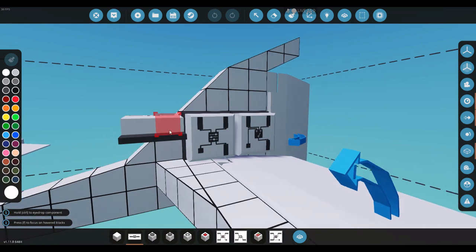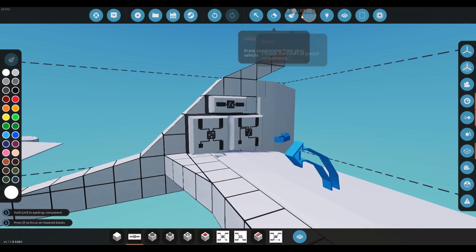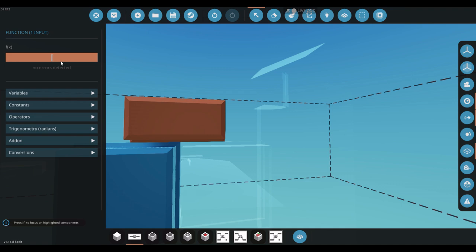And we'll put in the function block over here to keep things nice and simple since we're still working on altitude hold. So for the function block, remember, we were getting 5 values greater than what we wanted. So we're going to hit x minus 5. If you were getting 5 values lower than what you wanted and you want to add more, you would add plus 5, or plus however many, or whatever the difference is, that's the number you put.